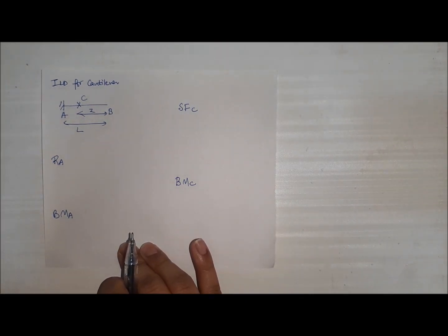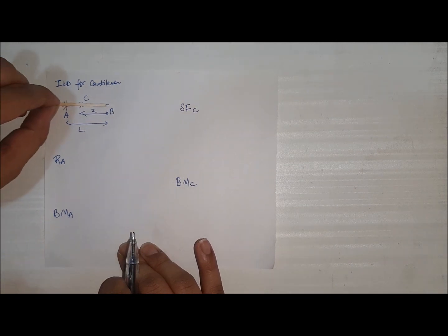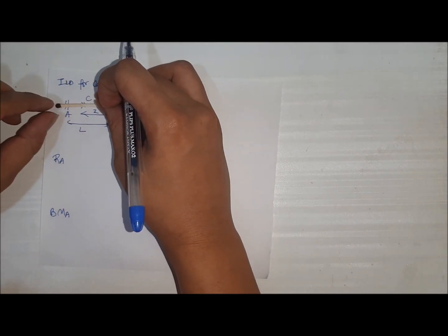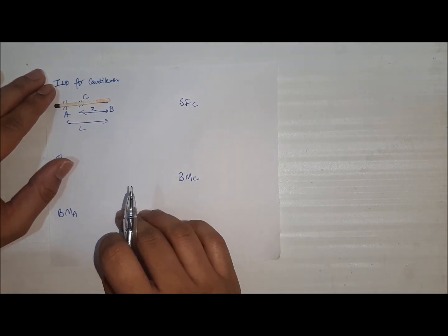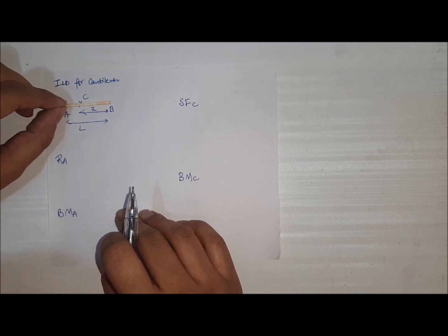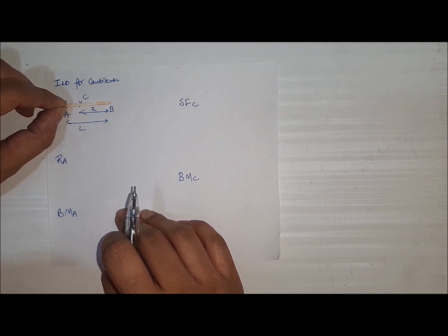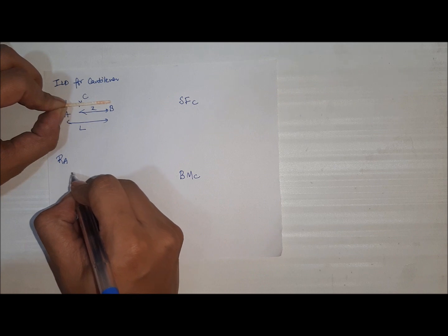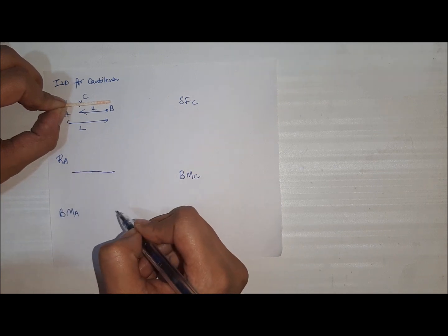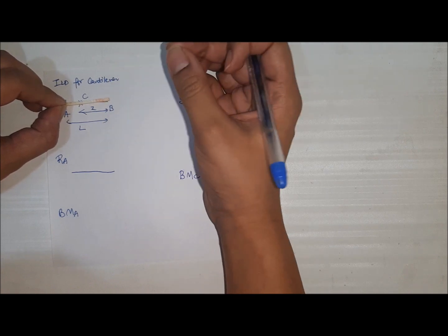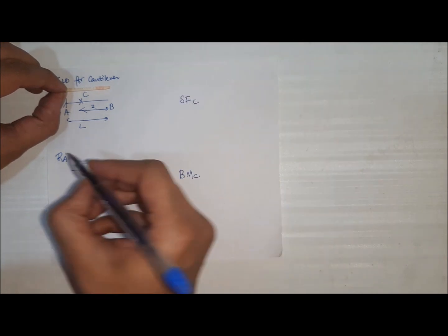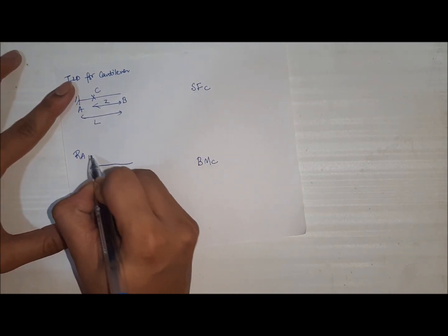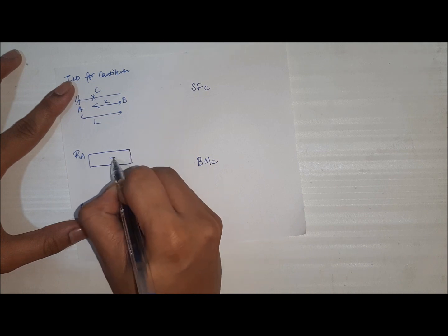We have the beam AB, and A is fixed. What we mean by the end A being fixed is that no vertical movement, no horizontal movement, and no rotation is allowed. So when we lift the end A with an ordinate of unit dimension for plotting the ILD, the whole beam will lift up because end B is already free. There is no support.